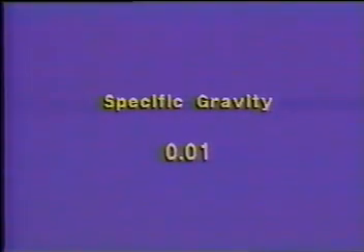When reporting the results of these tests, remember to report specific gravity to the nearest 100th and indicate the type of specific gravity, whether bulk or bulk saturated surface dry. Report absorption to the nearest 0.1%. Note in your report if the specific gravity and absorption values were determined without first drying to constant weight at 230 degrees Fahrenheit plus or minus 9 degrees.